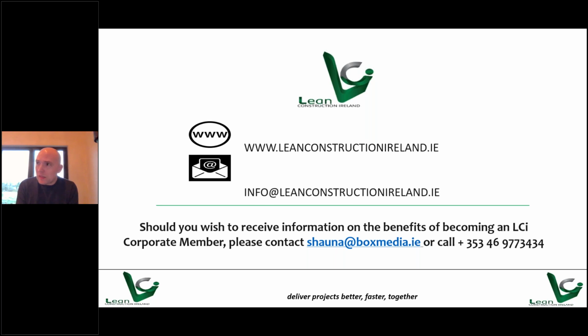Embodied carbon and material reuse are probably two of the biggest ways of demonstrating that we are being as lean as we possibly can. And it's really just about benchmarking against other buildings as well. So almost having a database of similar buildings, but also drawing on our own experience. We know what slab thicknesses, for instance, we're expecting for certain spans of buildings. We know the design loads that we're expecting, that might fall out of the client's brief due to the use of the building, and then going back and interrogating the stakeholders and the client's brief as much as we possibly can.